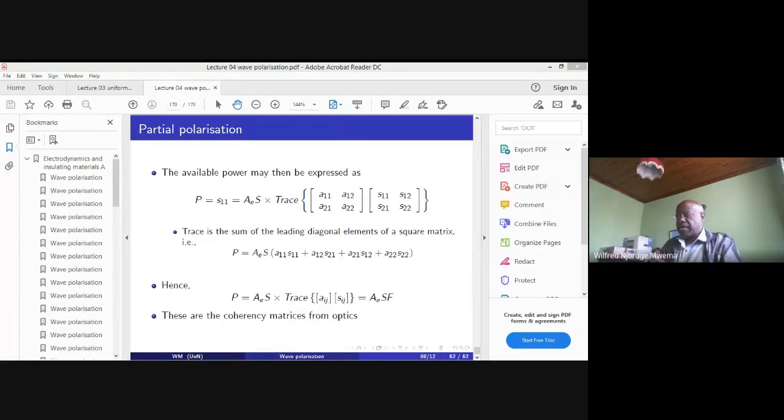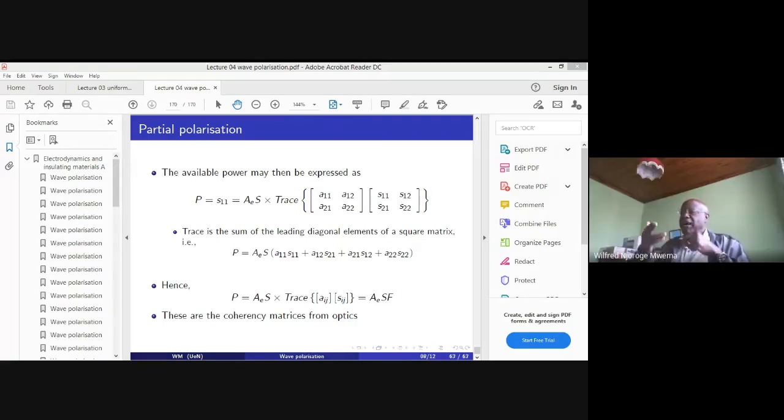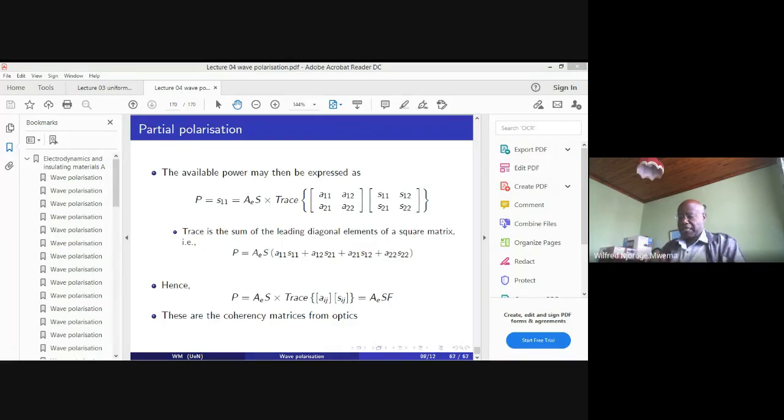So that K squared is a general one. But when we split this into axial and transverse components, we have said that in the z direction the fields behave as e to the minus gamma z. If you put it into the equations, you get a gamma squared.